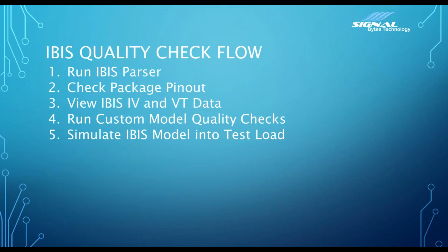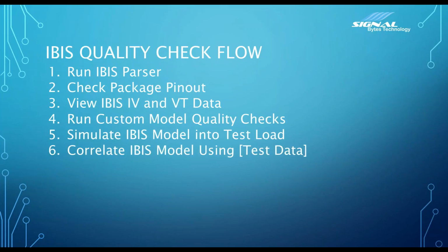And then you should always simulate the IBIS model. You can start out into a test load, maybe do a simple transmission line load as well. But really what you want to do is simulate it into some sort of test load before you drop it into your full-level simulation. That way you know the model's good before you start simulating, and then have to debug a whole simulation flow, whether it's your package models, your PCB models, or the tools. So it saves you a lot of time and stress to do it like that.